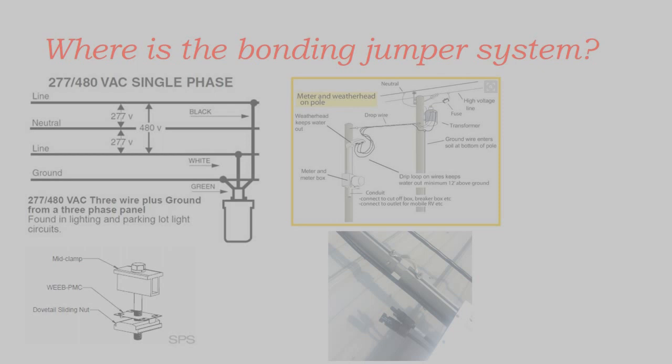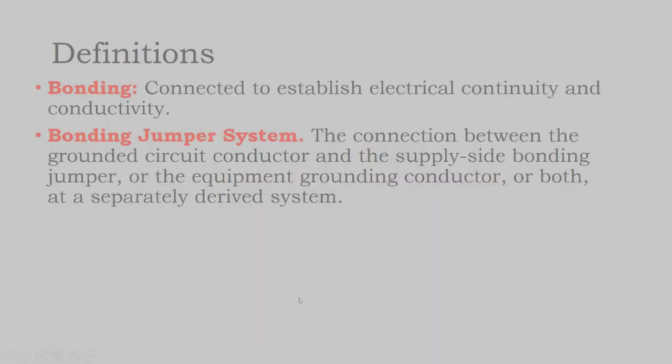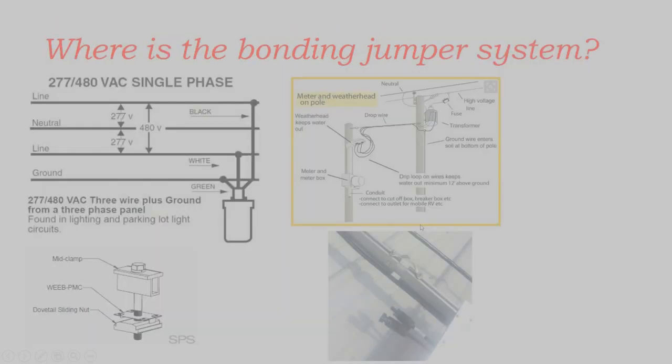And so you might have your solar rail that is metal, and your modules are connected to your solar rail, but that doesn't necessarily mean they have the electrical connectivity. They need to conduct electricity, and whenever metal has an anodized finish on it, instead of being a raw piece of metal, they coat it for corrosion resistance, they coat it for aesthetic purposes, and that coating eliminates the conductivity.